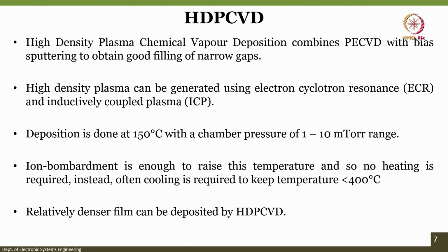So, deposition is done at 150 degrees centigrade with a chamber pressure in the 1 to 10 millitorr range. That is another thing that you need to keep in mind, that the deposition is done around 150 degrees centigrade. Second is that ion bombardment is enough to raise the temperature. So, no heating is required, instead often cooling is required to keep the temperature less than 400 degrees centigrade, and a relatively denser film can be obtained with the help of HD PECVD.